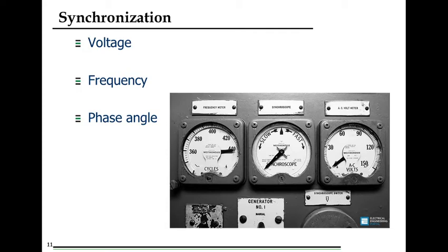You'll notice that the generator and mains are not connected directly through one input. They are connected with a three-way switch, one side of which has the main supply, the other side has the generator supply, and the middle one is in the off position. This off position may or may not exist in some cases. This means that the generator and our main supply cannot run in parallel while supplying power. Either the mains or the generator will be supplying power to our domestic load.